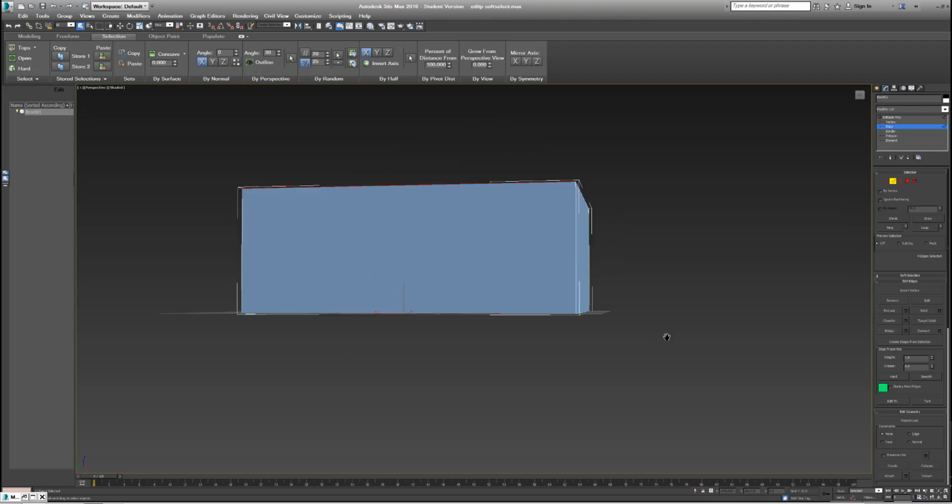So basically what I want to do is create a vertical segment that's sort of bounding these horizontal edges all together so that I can start to move them about and create some delineation for a window. So I'm actually going to hit this connect key now. And what that does is you can think of the connect as shaking hands between each edge. So we're drawing a knot or drawing a link between each of these edges.